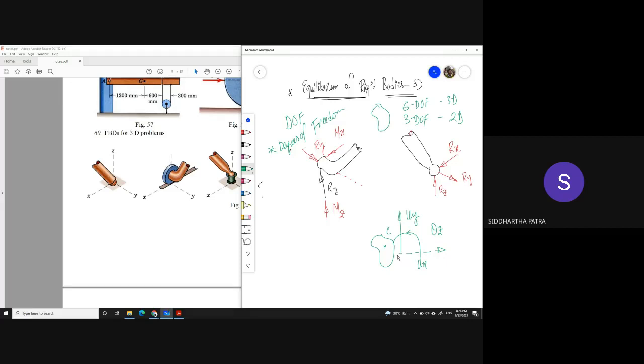So irrespective of whether or not it is moving a certain distance in x and y, it can independently rotate. A rigid body in 2D, if it is free, has 3 degrees of freedom. And it can have 6 of those in 3D: translation in 3 different directions, and rotations about 3 different axes. So that accounts for 6 degrees of freedom.